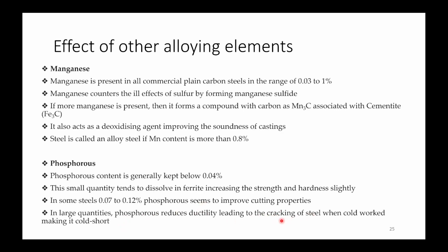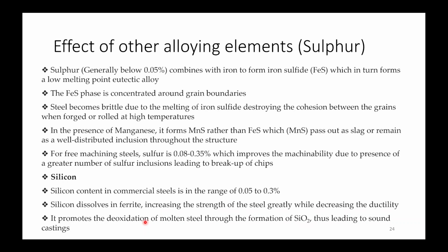So you are restricted at your lower temperatures; you can't use the steel at lower temperatures. I mean, in hot shortness, actually, it will be resisting the rolling. During rolling, it will be resisting it due to the presence of sulfur.